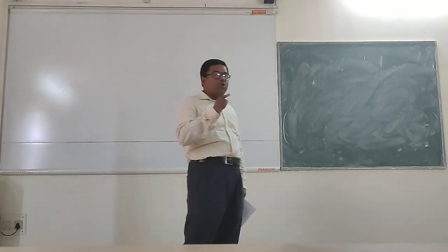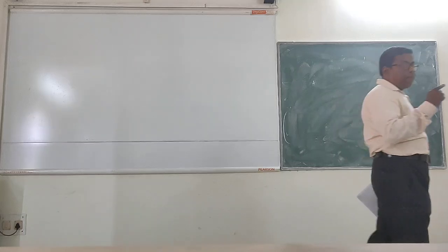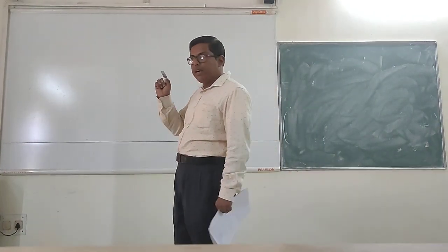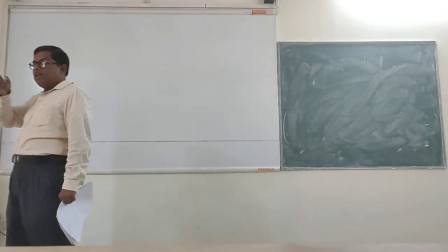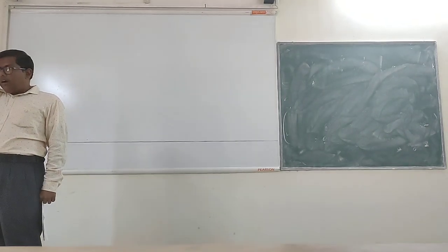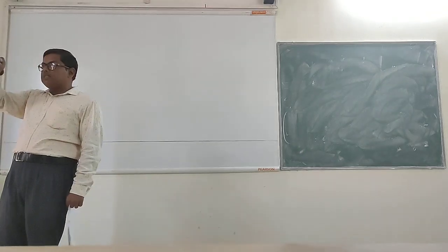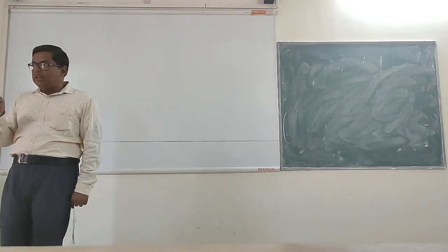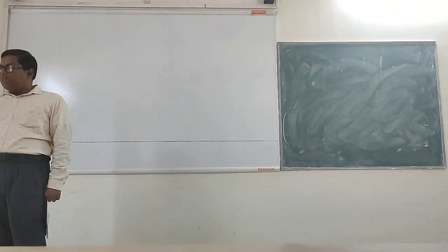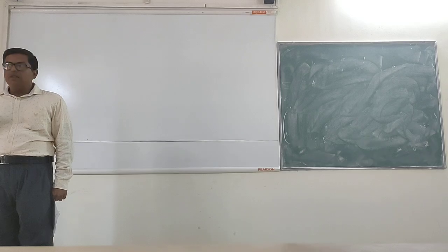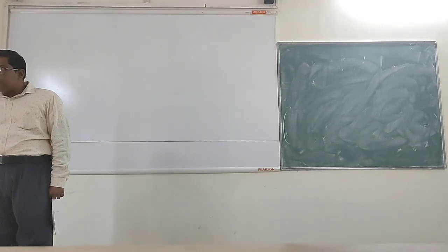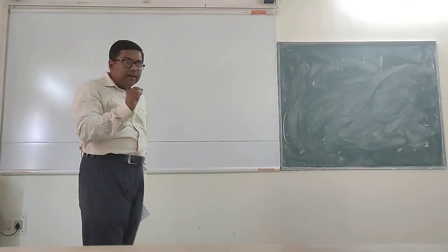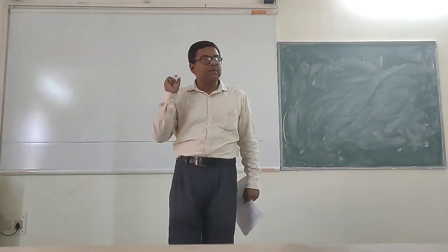Using Macaulay's method, we have seen that we can develop a generic equation for the moment, considering the section X put at different locations before the load and after the load. Then we get one equation. What is the assumption in Macaulay's method? If the terms become negative or 0 after putting the value of x, then it will be neglected. That is the assumption.